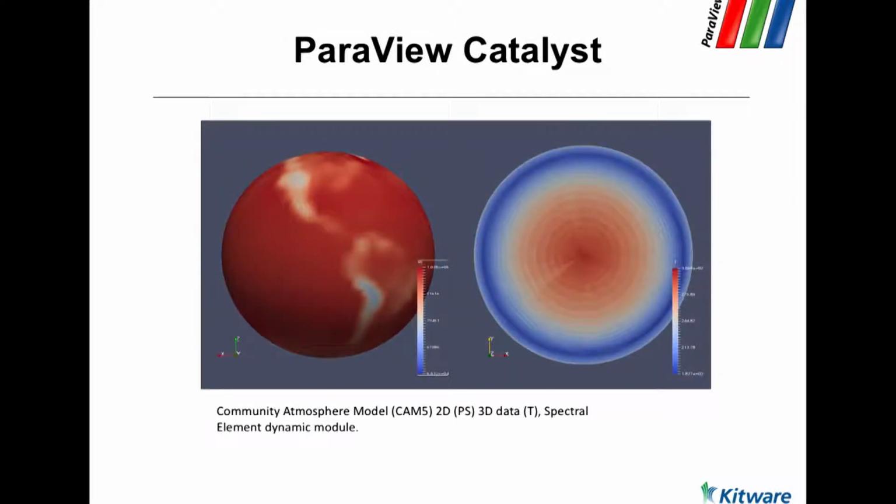And ParaView Catalyst was mentioned in the previous presentation. This is a library, a subset of ParaView that you link with your simulation and allows you to analyze and visualize the data for every time step of the simulation. So the simulation runs the time step, passes its data to ParaView, you run the visualization, you produce an image, and save it on disk.